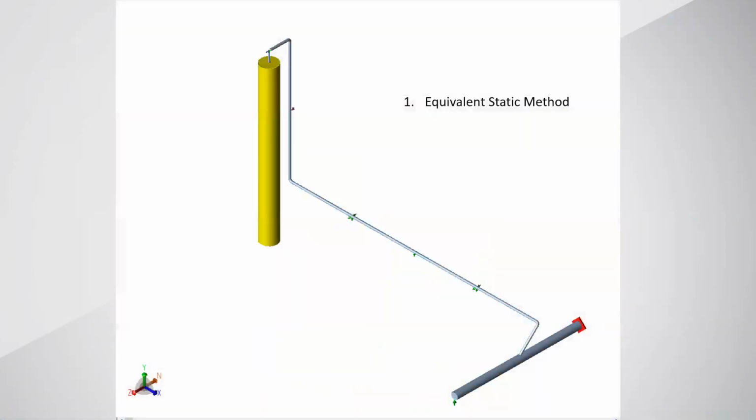Okay, so we're now ready to go back into our model and apply these things. So the first thing we'll notice is, as the relief valve discharges, we'll get a high pressure region just after the safety valve outlet, and that will be a high pressure system.